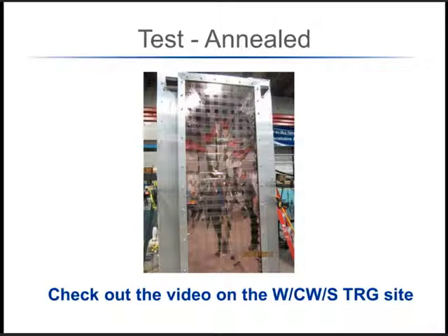We also measured, with an LVDT, the deflection at the center of the glass. So we basically put a vacuum on the glass and ramped it up and took readings of the deflection and also of the load at which the glass broke.